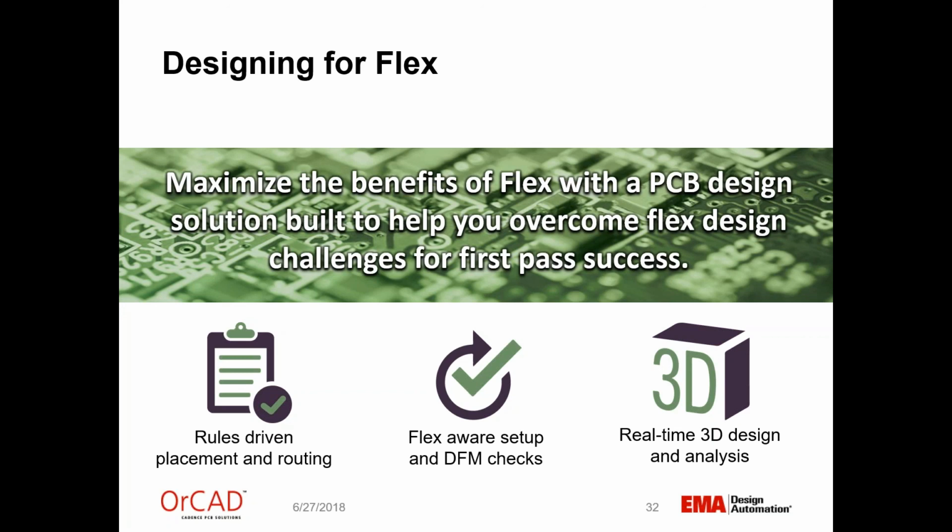Perfect. And we'll do one last question here. Is the 3D modeling of Flex limited to the full version of PCB Designer, or can it also be done in PCB Designer Standard? Yeah, the 3D viewer is available with every tier of PCB Editor. You have the right version. It didn't come out at the very beginning of 17.2. This version of the 3D viewer came out a little bit later. So just make sure you're up to date on your hot fixes.